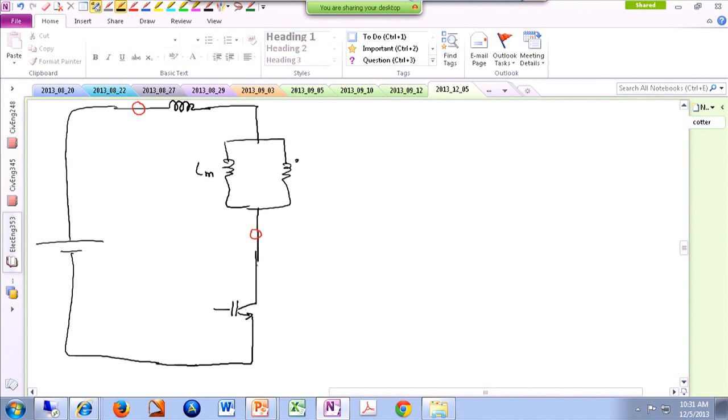So what you do is you add a cap to the system so that instead of the parasitic cap of the transistor getting charged from this leakage energy, that extra cap is going to be charged. So you add this cap over here, and then I'm going to explain why.